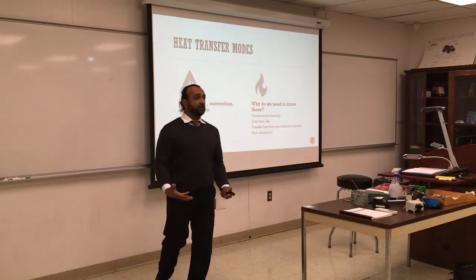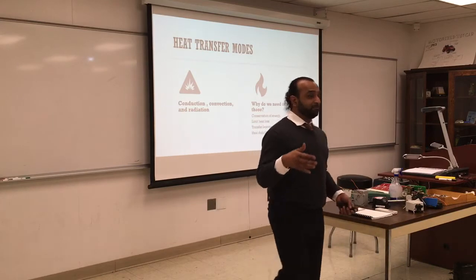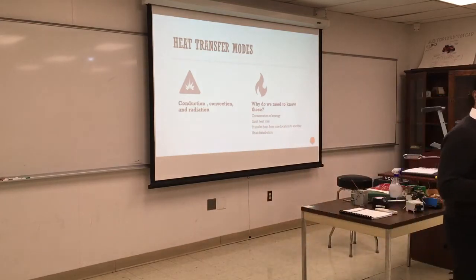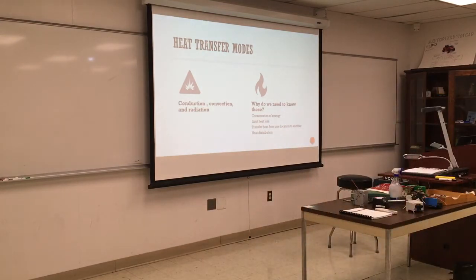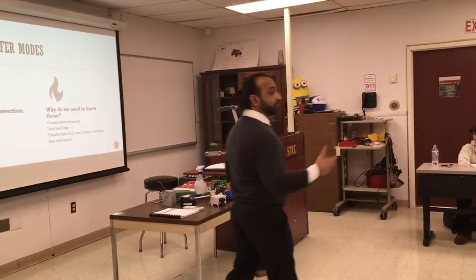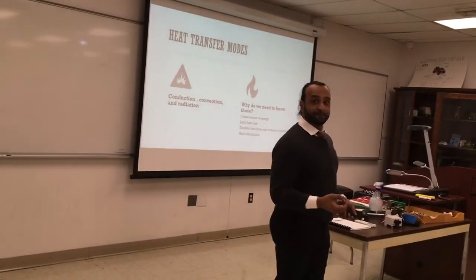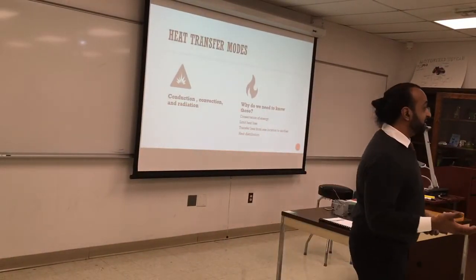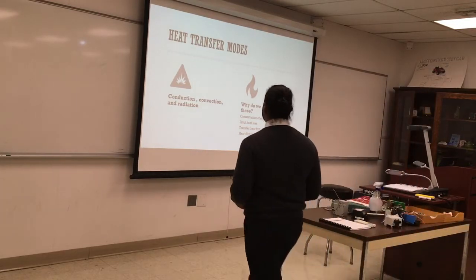Natural is when we use buoyancy. The basic idea is that the fluid, when it gets hot, it expands. It's less dense, so it rises. So eventually it cools and comes back down again. You have that lava lamp, where you can see the convection going up and down. It just keeps going over and over. It's natural, it's free, gravity is cheap, it's reliable, it's always the same.